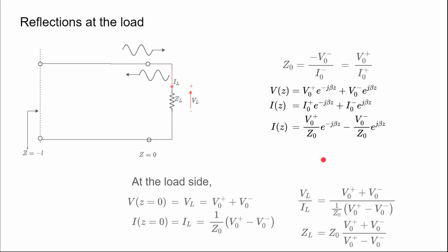We are going to form a relationship between the impedances in the line and the voltages in the line. To do that, we take the ratio of voltage and current in the line, and represent the voltages and currents using a parameter called the reflection coefficient, which is the ratio of the reflected wave over the incident voltage wave. We replace these equations so that we can find the reflection coefficient of this transmission line at a certain location.